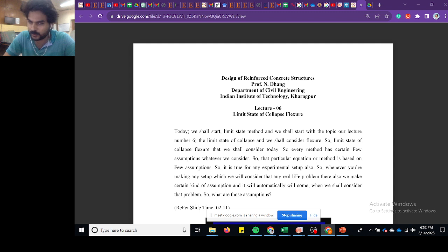But these days, no one uses this. If you go to the rural or semi-urban areas, I don't know whether it's the North India or South India scenario, especially Andhra Pradesh, only in urban areas are there very limited RMC plants. In most locations people still use volume batching on a small scale. Even in government projects they don't accept it nowadays. But weight batching is always better. Yes, weight batching is best.